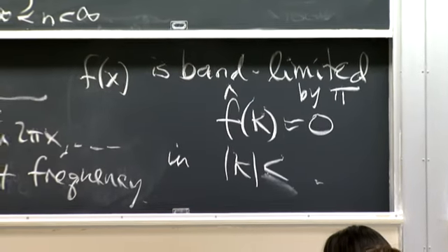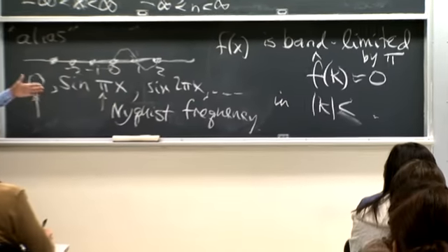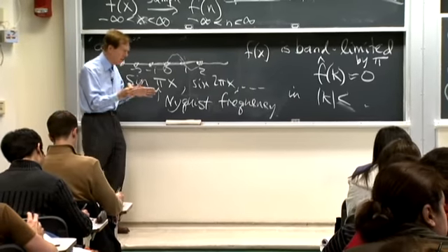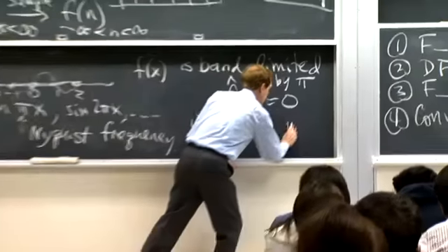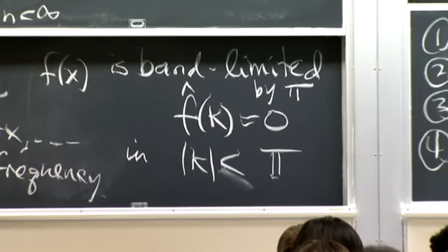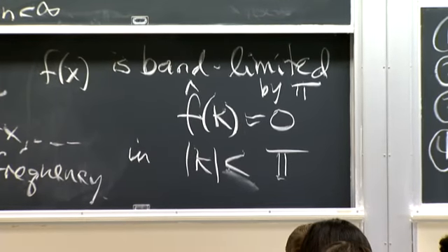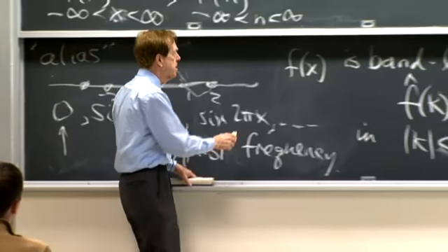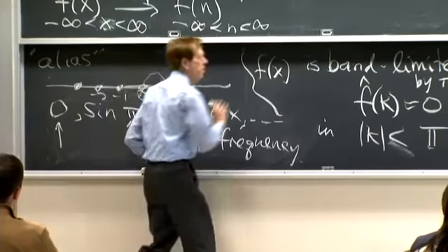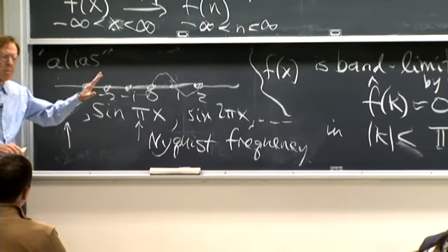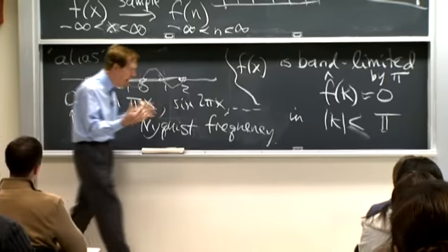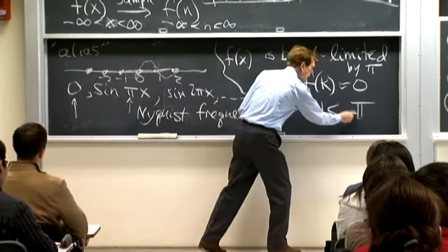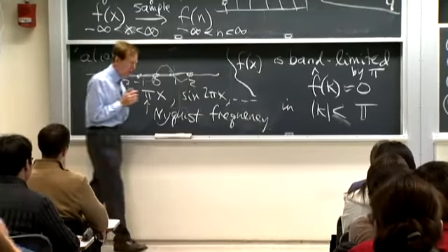And our interest is when that limit is the Nyquist frequency, the one we don't want to allow. So this is the point. This will be the idea, that if we take this class of functions, those are called band limited functions, and they're band limited specifically by the Nyquist limit.